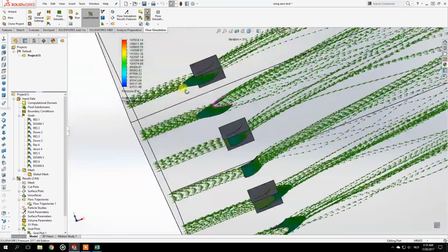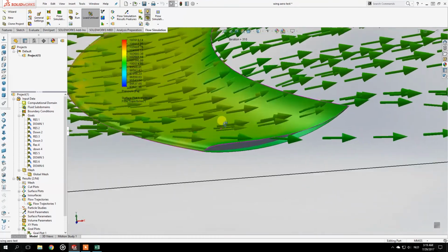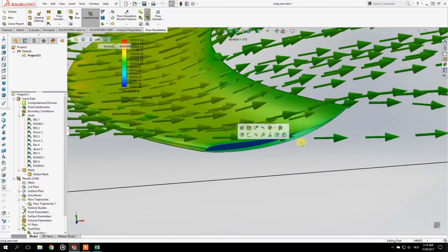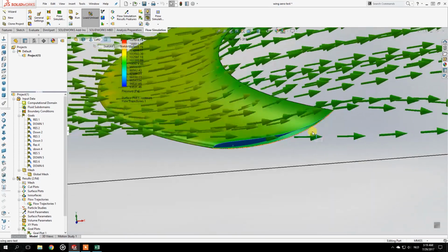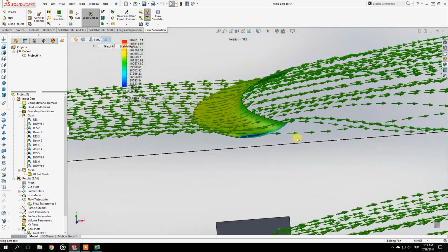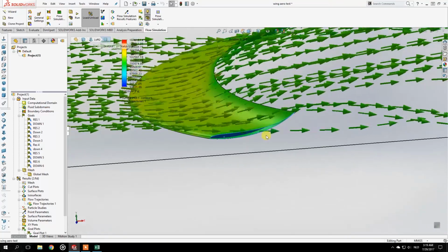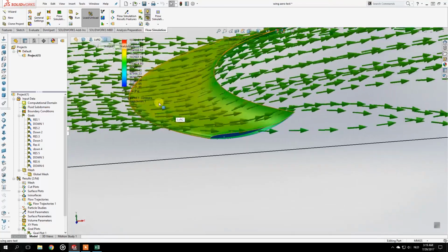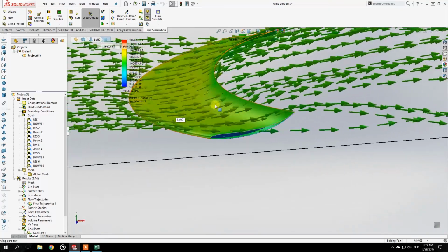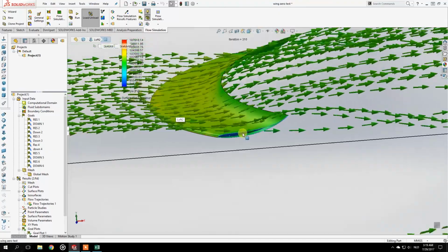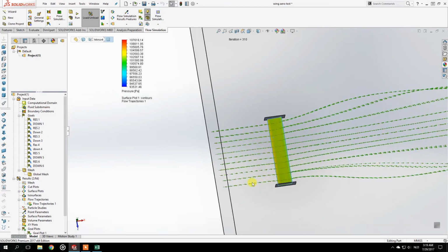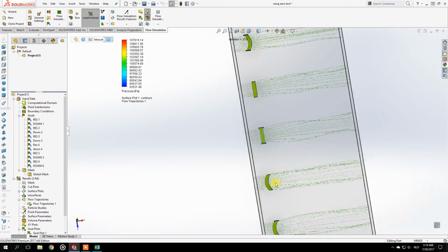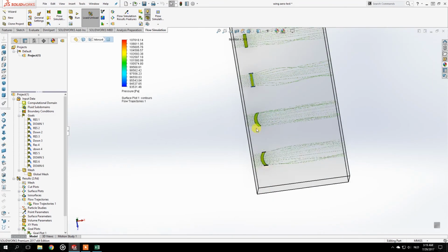So where you normally would look at the wing pattern and it would be this shape, it will get stretched out because of the approach angle that it's taking. So that makes the wing a little bit less aggressive, and it isn't trying to direct the air upward with the same amount of energy as it would in this straight situation with all of those air currents just traveling in a straight direction, if that makes any sense.